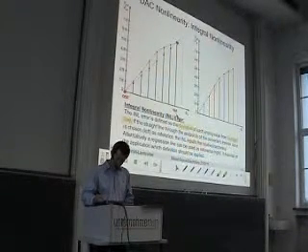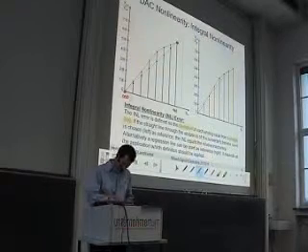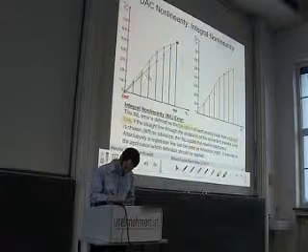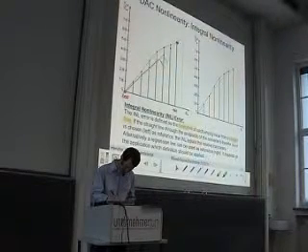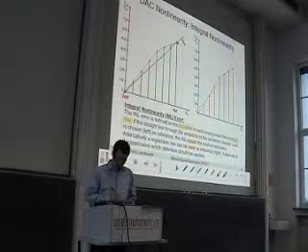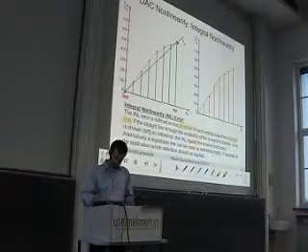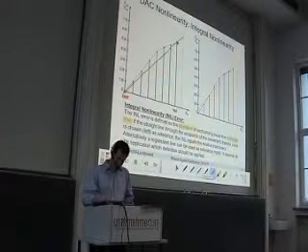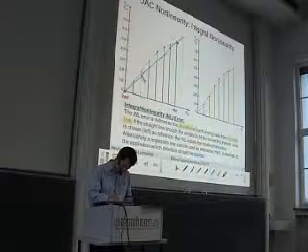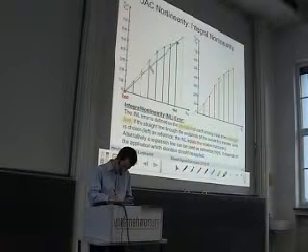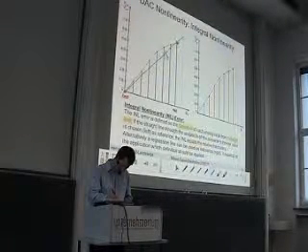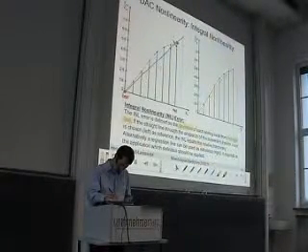This is my reference line against which I measure the integral nonlinearity. So let's take these 2 points, connect them, and we get a curve like this. And the integral nonlinearity now is defined as the deviation of the analog value from this ideal line. So this is the integral nonlinearity.